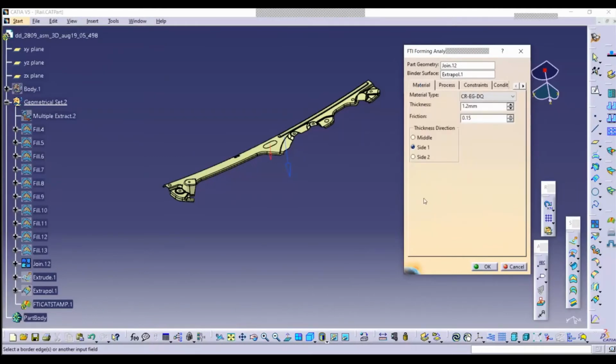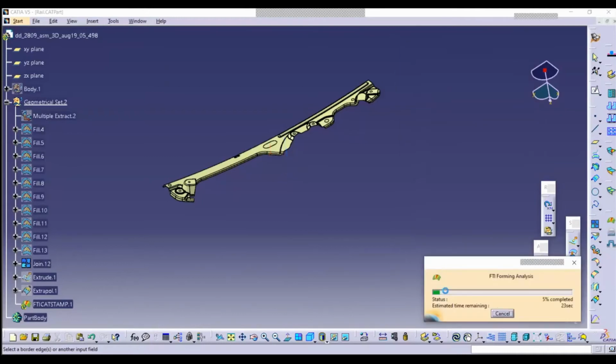So once I've defined all of my parameters, and of course you can see as I'm explaining it, it is a little bit slower, but we enter all of those values and then we're going to choose OK to run the solution. So I'll say OK, it's going to mesh the part. It is then also going to run our solver. And then once the solver is done, a dialog is going to pop up asking me if I wanted to start to display various results.